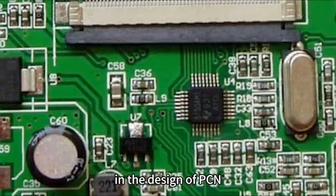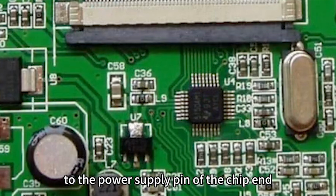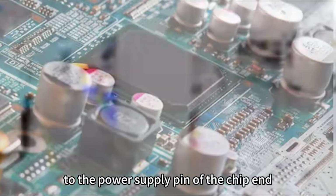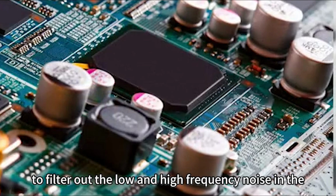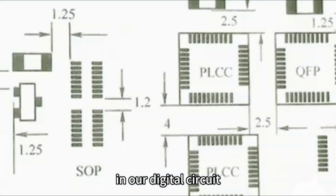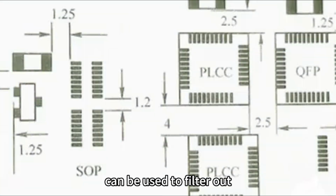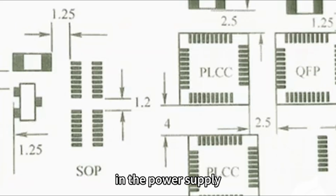In the design of PCB, the filtering capacitor should be as close as possible to the power supply pin of the chip and keep the power supply, capacitor and ground in the same straight line, so as to filter out the low and high frequency noise in the power supply. For example, in our digital circuit, the filter capacitor can be used to filter out the low and high frequency noise in the power supply.